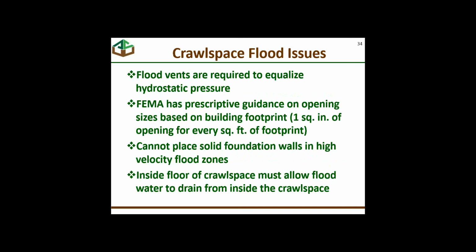There are some flood issues related to crawl spaces. We need flood vents in foundation walls in floodplains in order to equalize hydrostatic pressure. FEMA's got prescriptive guidance on how many of those flood vents you need, or at least in terms of the number of area of those total flood vents. And then there is some prescriptive guidance on how they should be spaced, how many you need in each wall, etc.